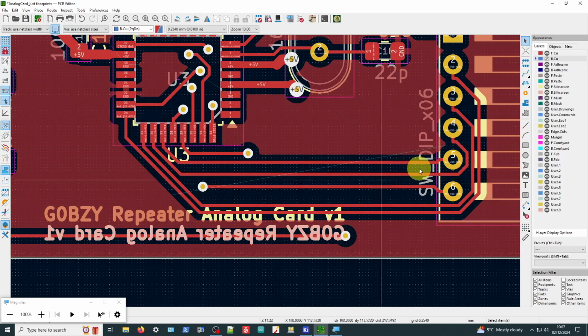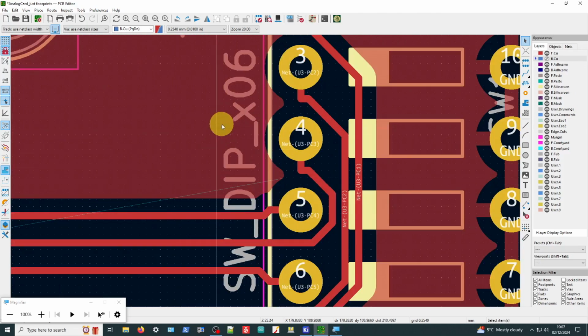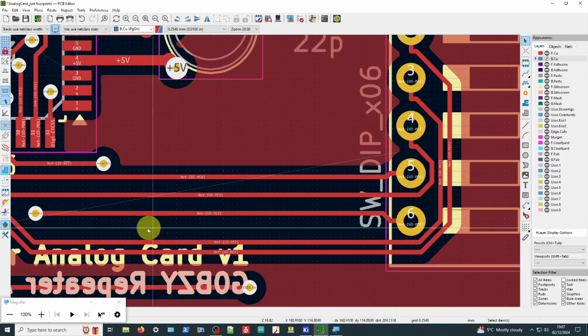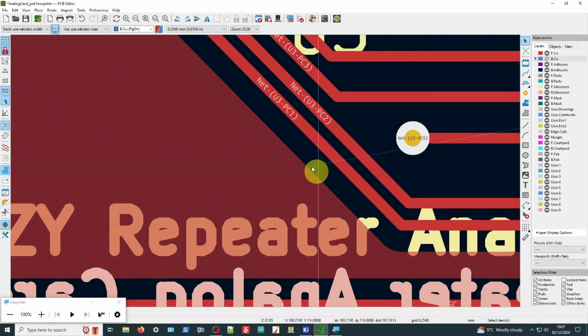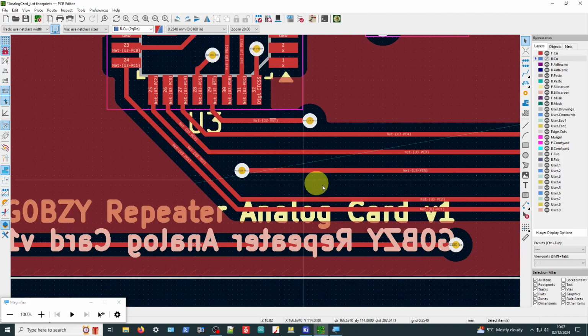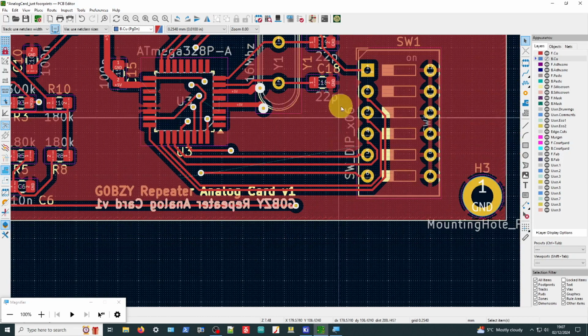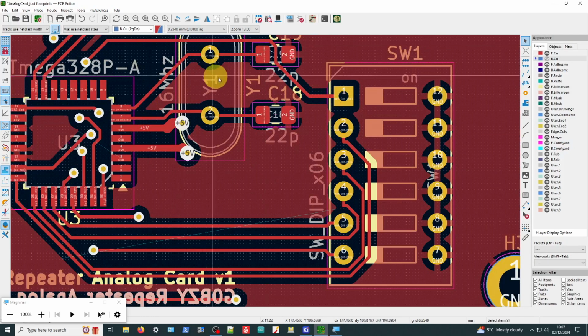And what that probably means is, if you can see this, it's coming from the copper fill here, and it's coming down to this part of the copper fill, and it looks a bit odd. They're not pins or anything. It means that this copper area here is probably not grounded. You've got these insulated areas around the copper fill, and if you look around there, it's insulated all the way around. So this copper fill here is not connected.